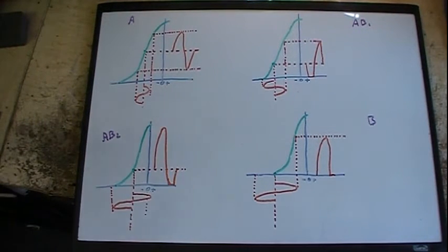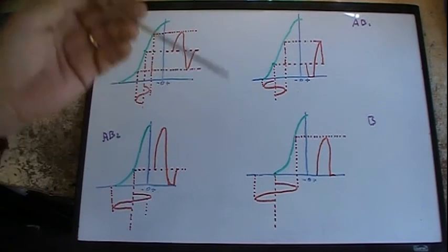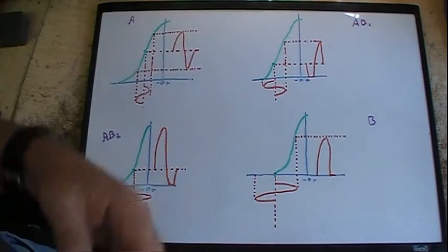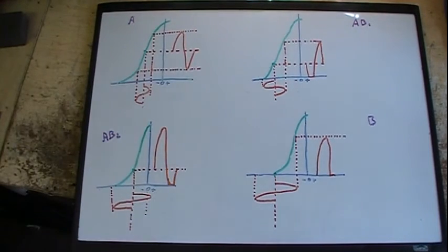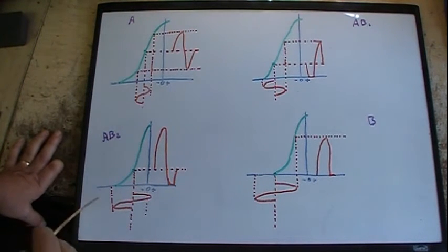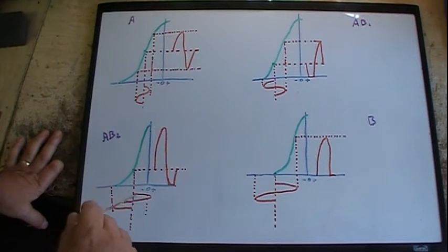Of course, if you got a battery operated set, you can also pull it off the C battery and just pull some current off of it. That's another form of fixed bias, except it's battery. But in those sets with fixed bias, that's got a power supply and the transformer and stuff, they'd set that up with that voltage divider, and then they had ample current when they needed it.